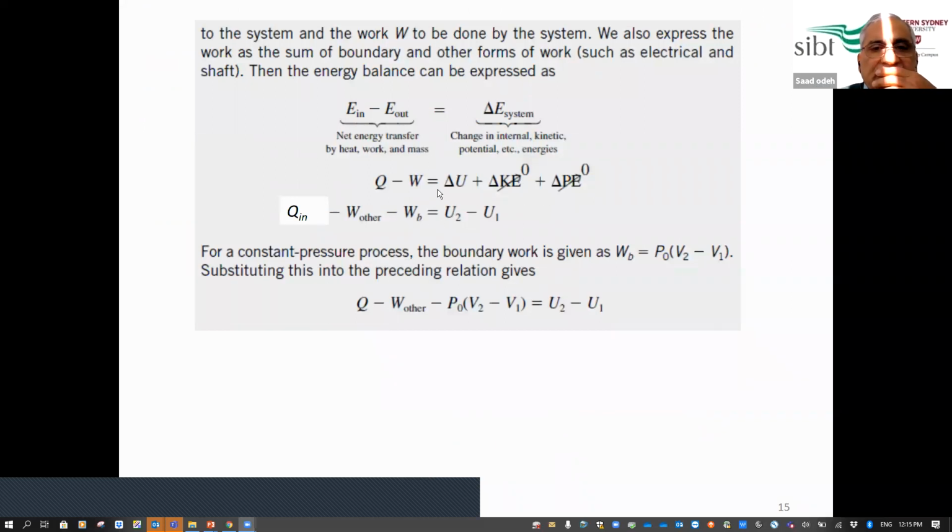We know that the equation we have should include Q because we have heat loss from the system. We should include also W because this is the work or the power of the electric resistance. And also we should include the change in internal energy of the steam because we are changing the temperature of the steam, then this must also change the internal energy of the steam.